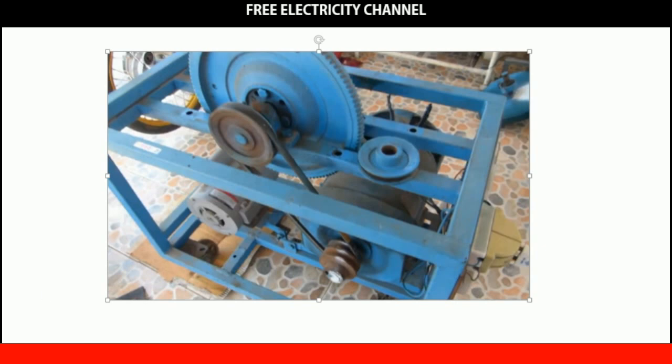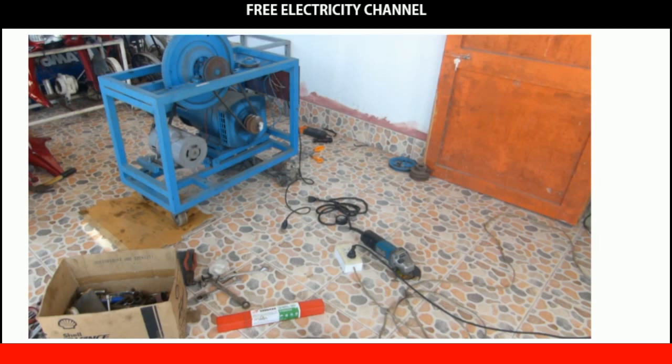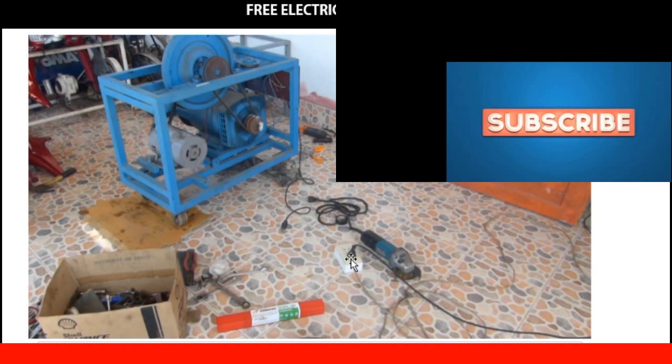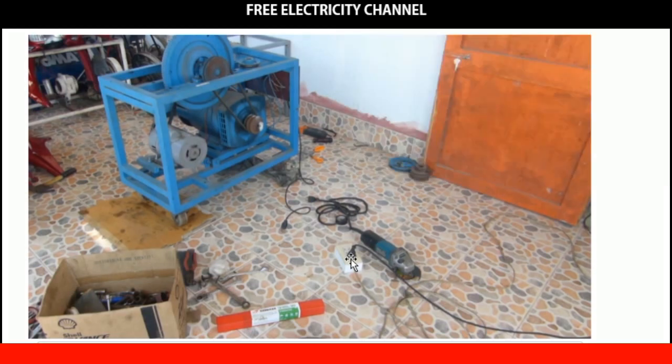Now let's take a look at this production, and we'll get a little better understanding. Look at it now. You can see the typical view of this. If you look at it, you see that this is the cable that enables the external power source to be released, and this is the external power source here. When this cable is entered here, and you plug it here, the generator starts running. Then when it runs for some time, you do what we call switching. You switch over from the external power source and then go ahead and do what we want to do. Now let's take a look at what we are saying.